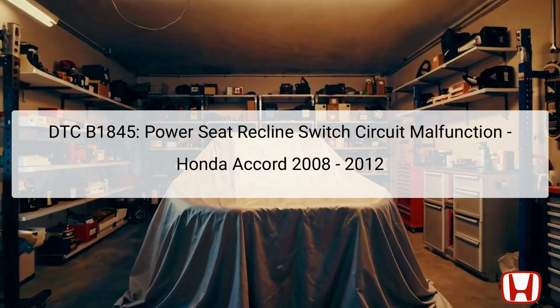The power seat control unit is typically located under the driver's seat, allowing connection to various seat adjustment functions. The power seat adjustment switch is also usually found on the side of the seat, giving the driver control over the seat's recline angle. Understanding this DTC is crucial in determining if the electrical signals are interrupted due to malfunctioning parts or connection errors within the system.